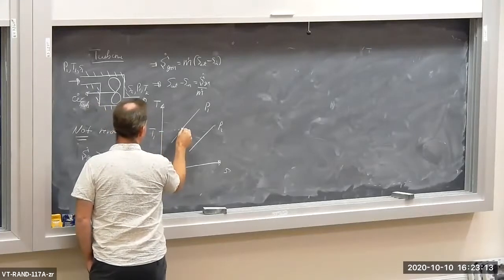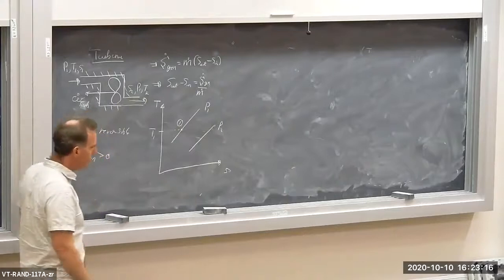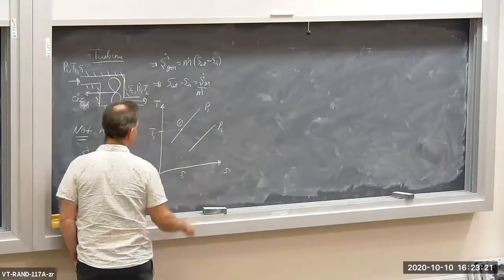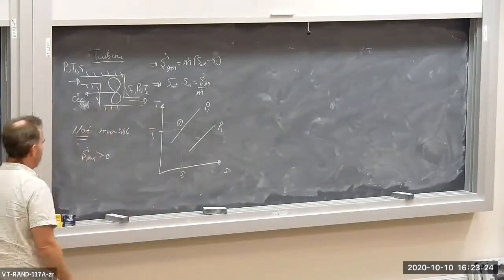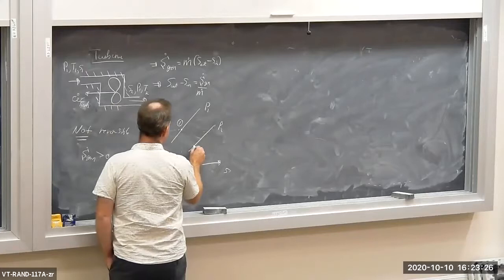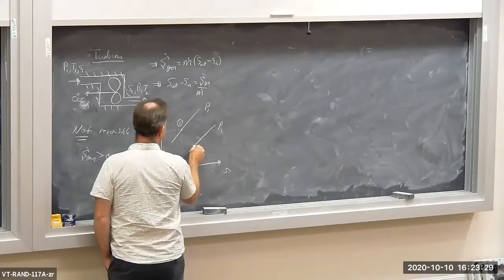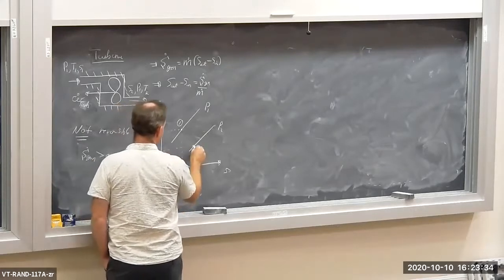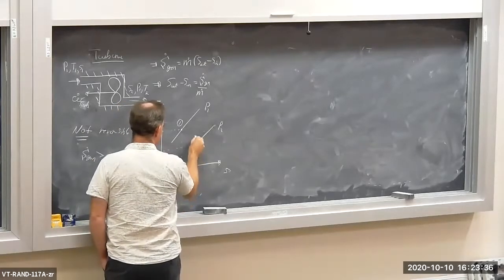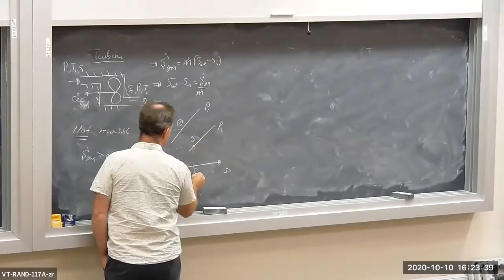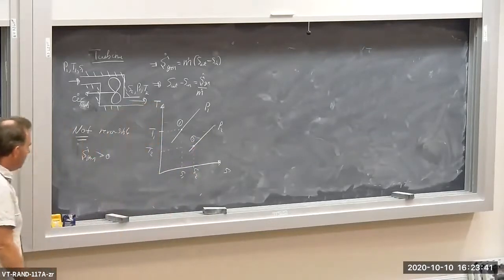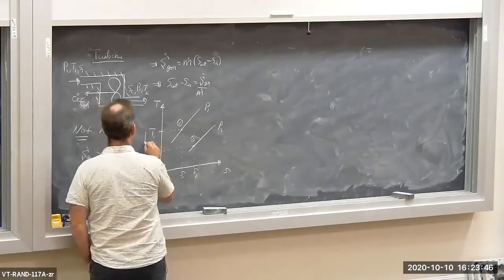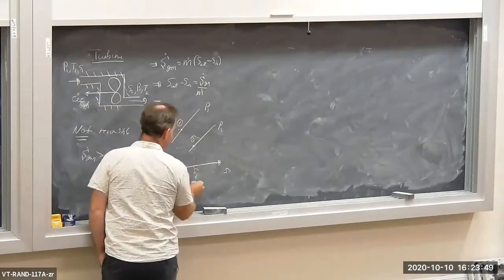So the inlet state, this is the inlet state number 1. And of course, I have an inlet specific entropy, S1. And then I decompress down to a pressure P2 and a temperature T2. So this is state 2 right here. And this is S2. So temperature falls. I extract some of the energy in the form of work. There's some irreversibilities inside.